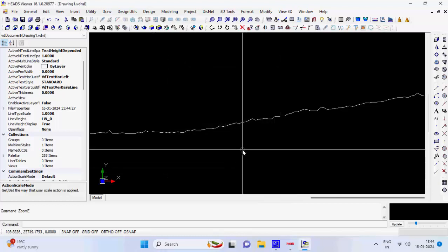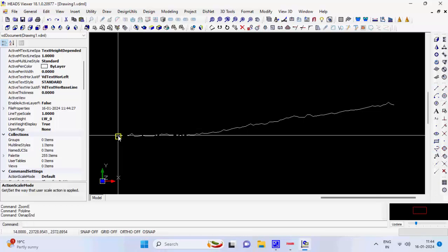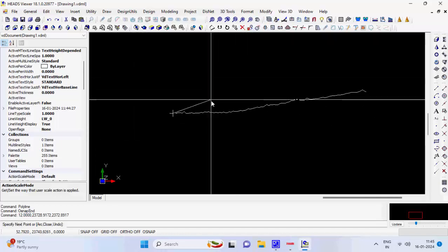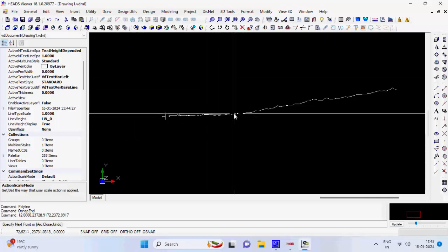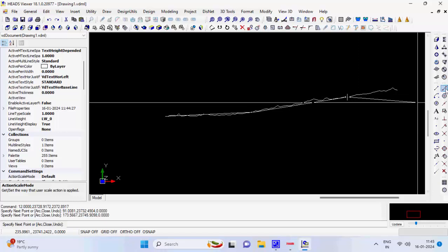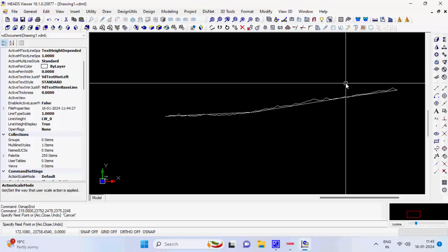Step 61, the as built long section is displayed, click on icon on the right side of the window as for drawing a polyline, and click on a number of points on the ground long section to draw a polyline. To finish the polyline click the right mouse button. The polyline should pass as close as possible to the ground long section, the points should be sufficiently away from each other to accommodate curves to be set at these points. These points are called vertical intersection points, VIP.